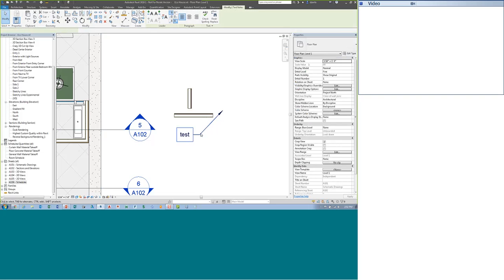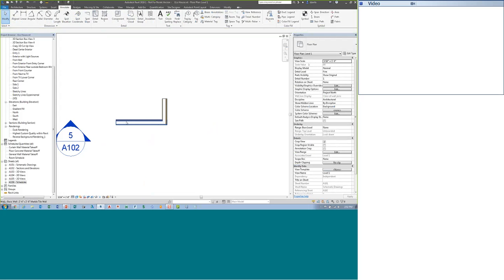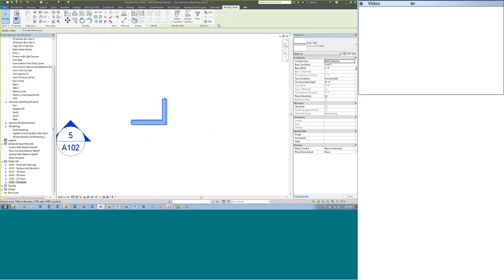Now there is an interesting feature in the software called selection sets, and I'm going to use this as an example. If you head over to the Manage tab of the ribbon, under Selection Panel, you can click Edit, Load, or Save. The way this functions is if I select entities, by default that selection panel will come up in the contextual tab. And I can click Save to save those objects as part of a group, if you will. It's not really a group in Revit, but it's a grouping and selection set. So I'm going to call it partial walls and hit OK.